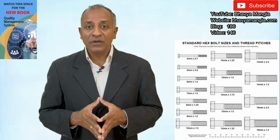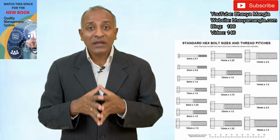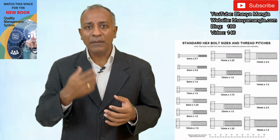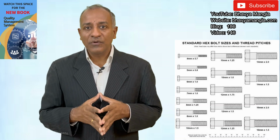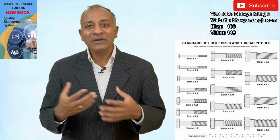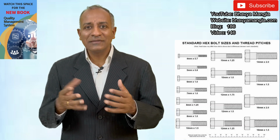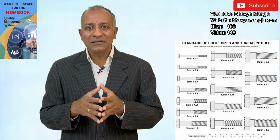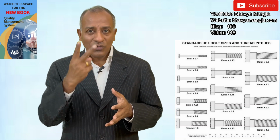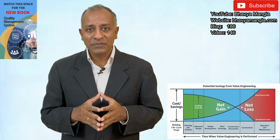Take an example in an assembly process. There are different kinds of screws that we are using. It can be M3, M4, M5, and it goes up to M10. For each type of screw we are using different width, different inventory, different suppliers, and different traceability and identification processes. But if we analyze and see that we can standardize, instead of having 5 or 6 or 7 different kinds of screws, can we have only 2 types of screws, say M6 and M8, which can serve the entire purpose?